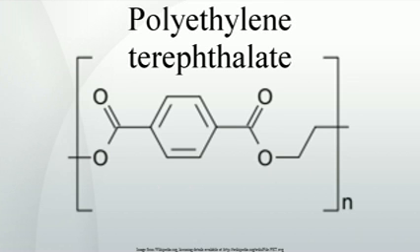This procedure is known as solid-state crystallization. When allowed to cool slowly, the molten polymer forms a more crystalline material. This material has spherulites containing many small crystallites when crystallized from an amorphous solid, rather than forming one large single crystal. Light tends to scatter as it crosses the boundaries between crystallites and the amorphous regions between them.